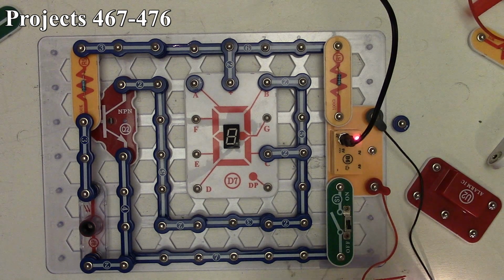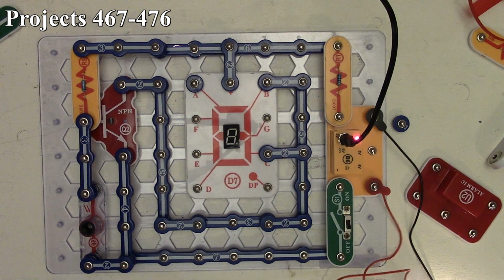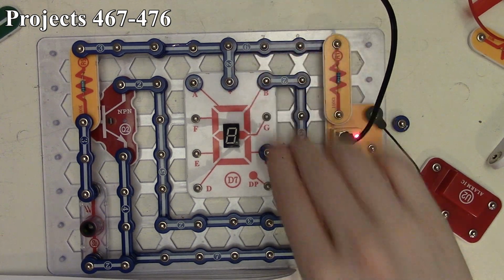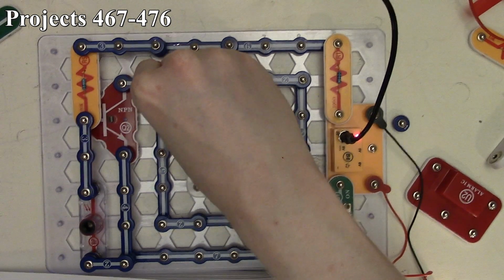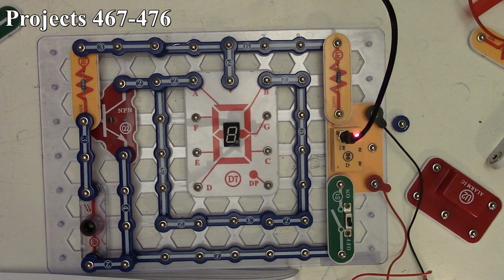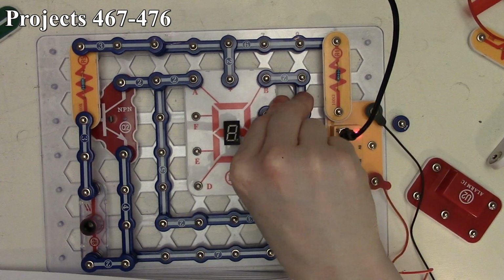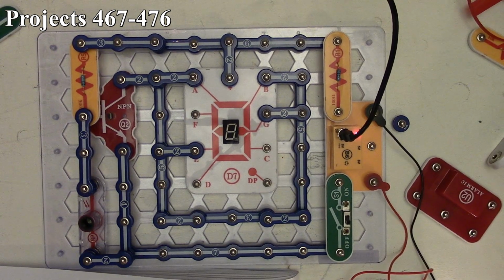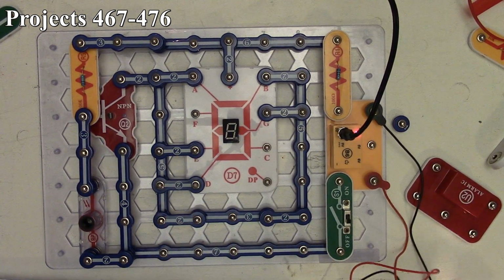Now Project 468 wants us to display the number 2 on it. So for that, we're going to connect A, B, G, E, and D. So we already got B there. We don't need C. We'll connect A. Get some more 2 snaps here. And let's see, G and E and D.